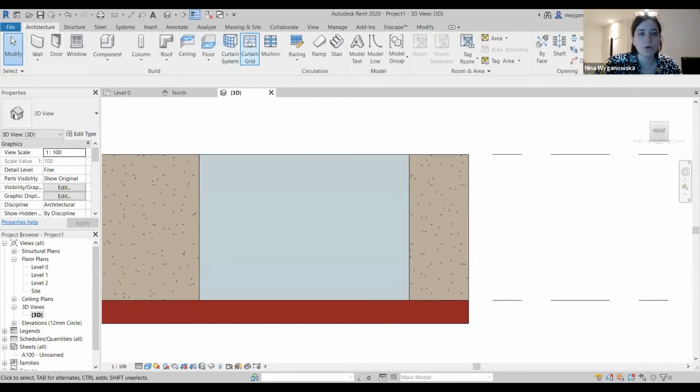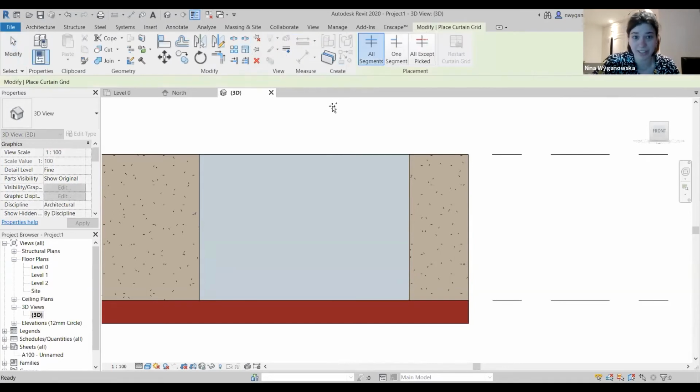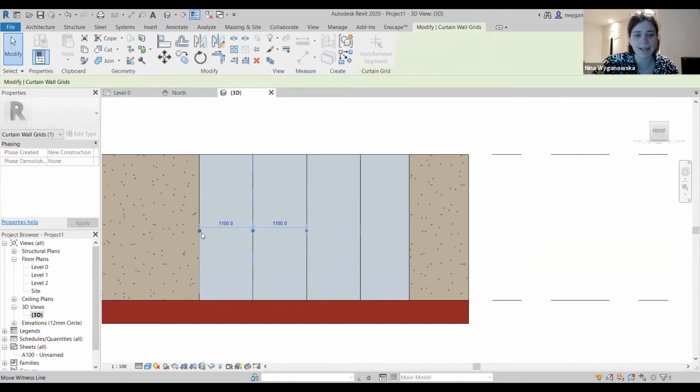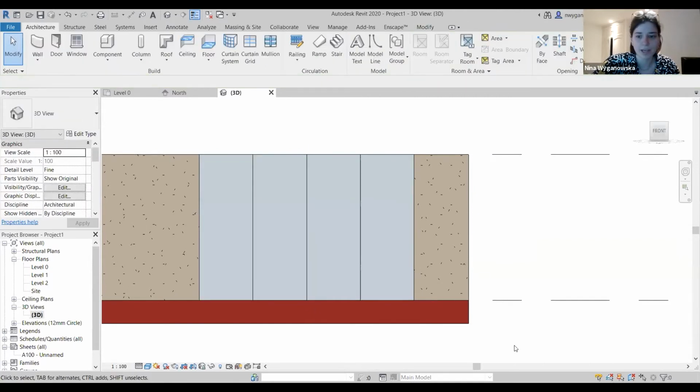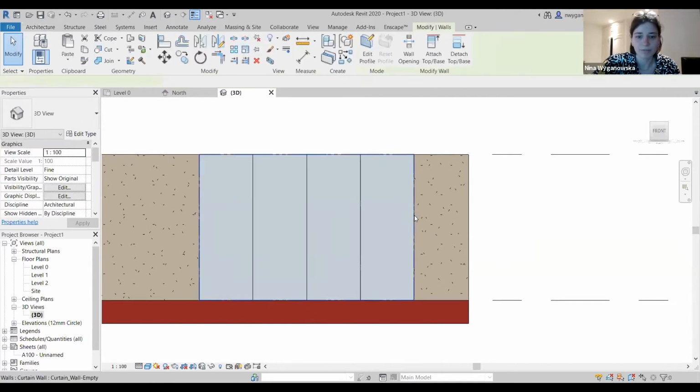But you can drag it as well along if you wanted, not any offsets. So to make it look like an actual curtain wall, you have curtain grid, and you can set it up basically by dragging any of these elements along. So whatever sizes you want, and you can adjust these sizes exactly like we adjusted anything else previously. So I want that stretched a bit.